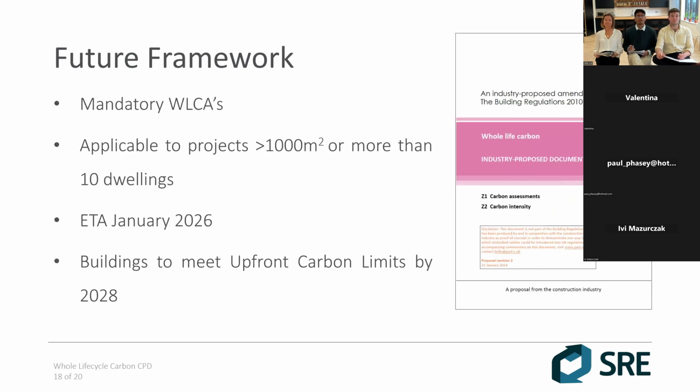Thanks, Adam. So as Adam explained before, building upon the national and local regulations, to enable further carbon reduction in the built environment, there is an industry-wide push for a new building regulation document called Part Z. This legislation mandates whole life carbon assessment for all commercial developments above 1,000 square meters and all residential developments of more than 10 dwellings.